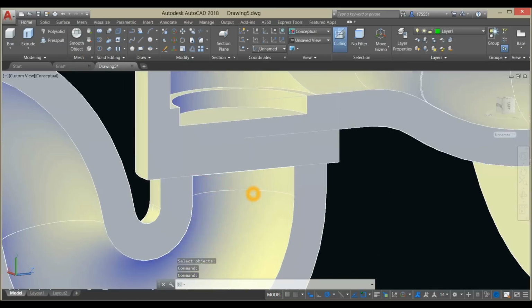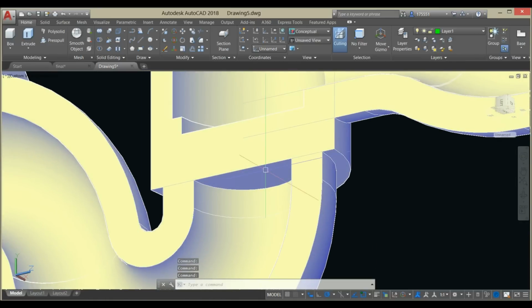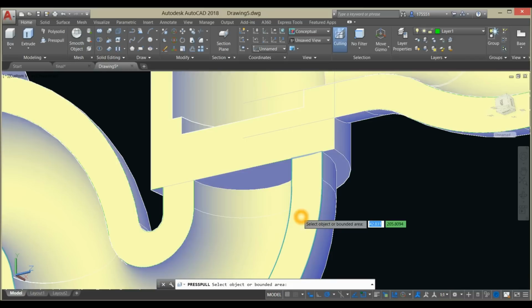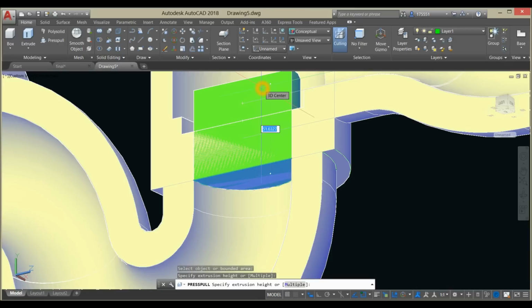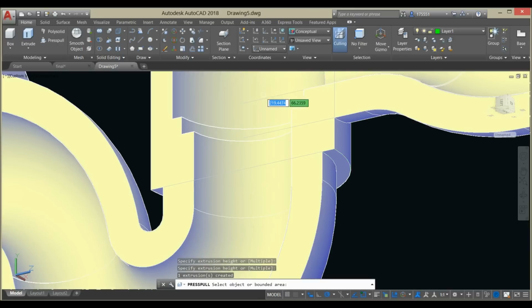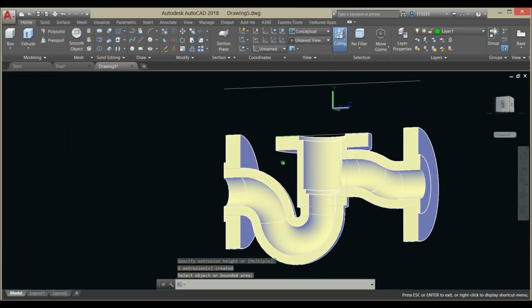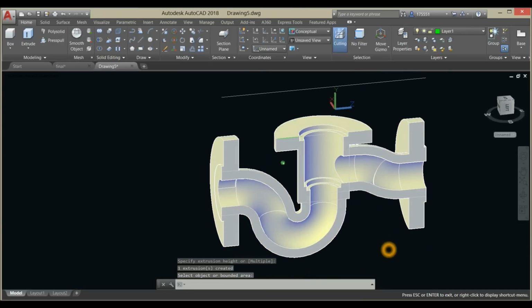And this one here, I could just use press pull command since this is flat. So inside the modeling panel, use press pull command, hover over this face here, left click, let go of your finger and left click again. Move your cursor upward first and left click again. There, that's easier. Now, I think we are done.